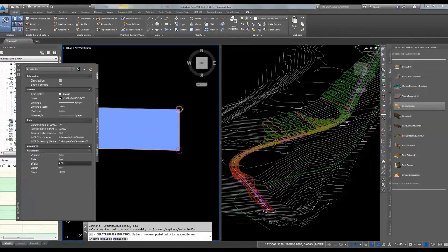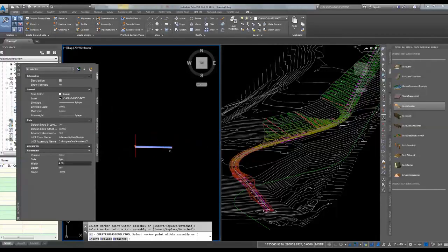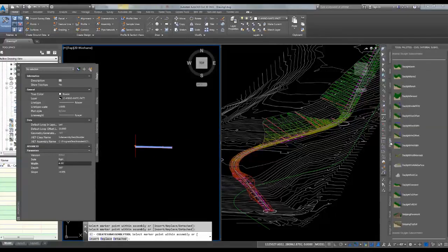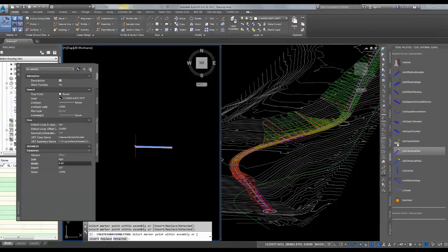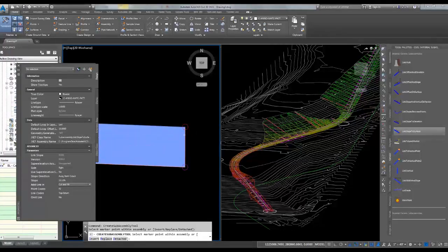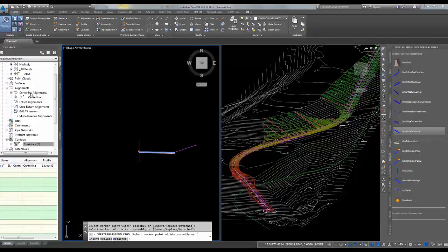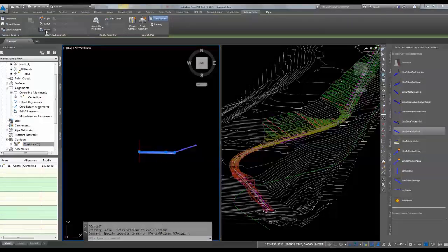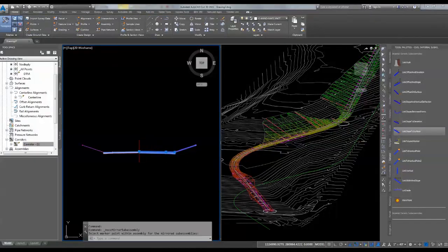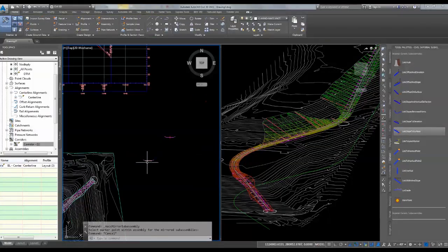So we'll add that in, and then I'll go back and I'll use, not the daylight, I'll use the generic, which is just link slope to surface. And again, on the right hand side, we'll set that to 3 to 1, and we'll add that here. Now this one, because it seems it likes it, we can mirror that one over about the center point. So we have to pick where we want it to go.